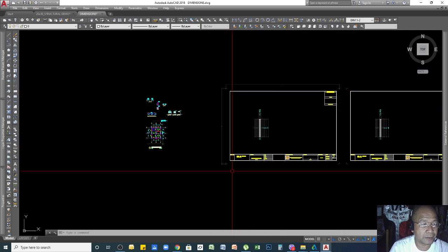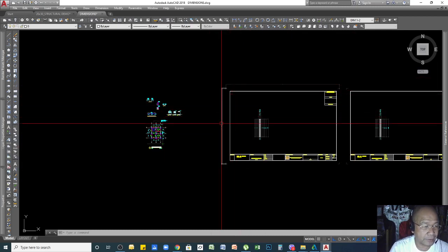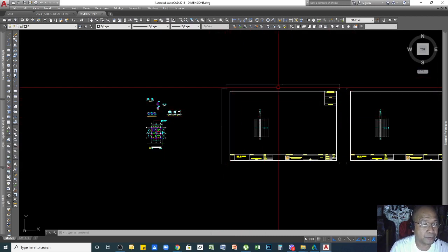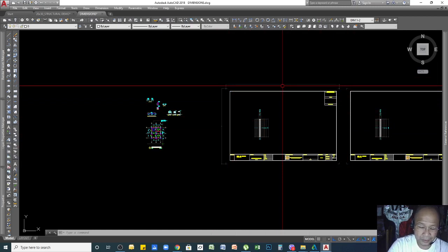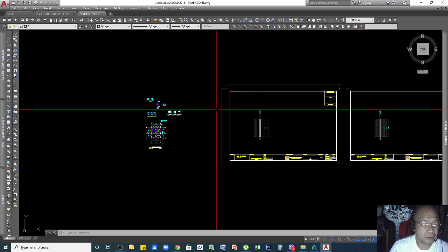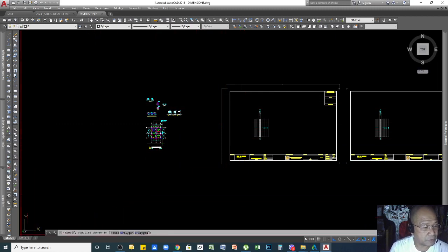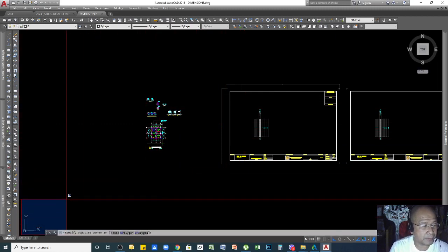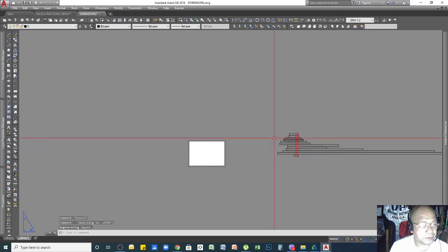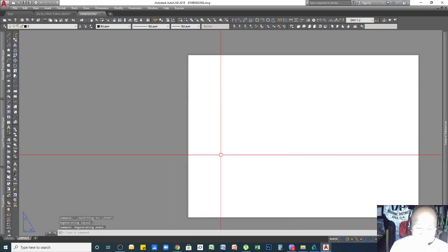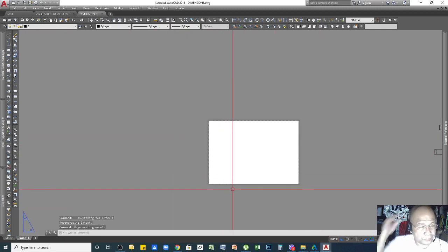Technically these dimensions are the width and the length, or rather the height, of your paper. If you convert this, it is equivalent to a 20 inches by 30 inches paper size. All right, so using the layout, we will set up our drawing space or paper space with that size.